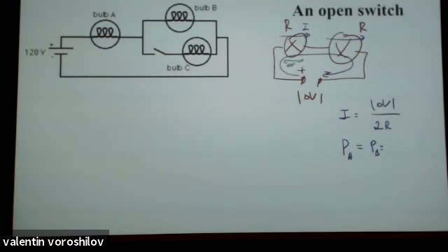The voltage on A is equal to the voltage on B, and it means the total voltage splits evenly. So A is equal to B, which means 1/2 of the total, or 6. So because I know voltage and resistance, this is my equation I would like to use. Well, technically I have to write delta VA squared over R.